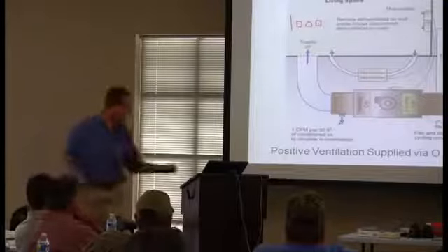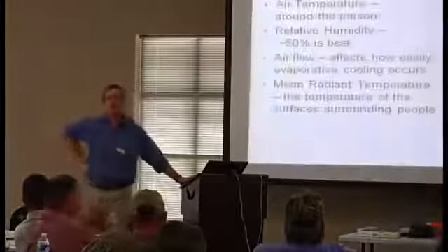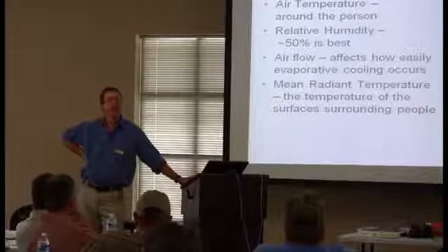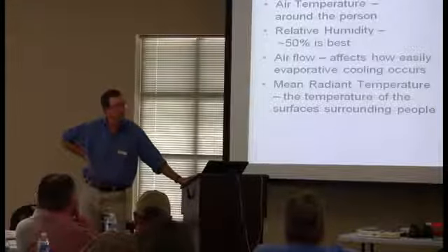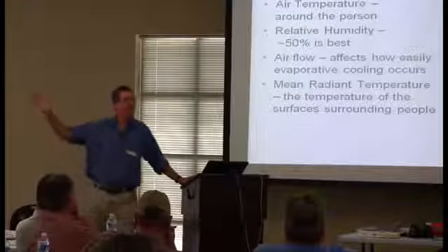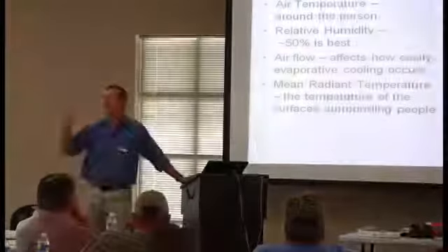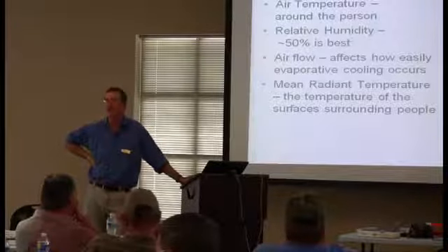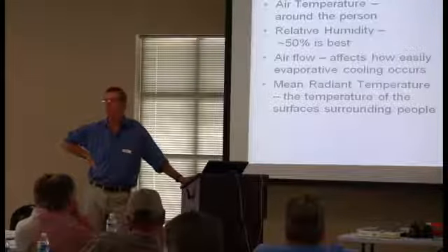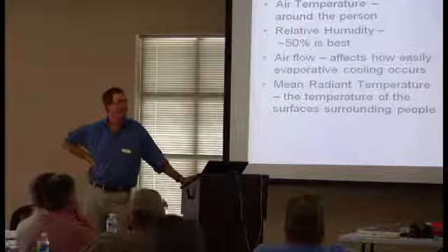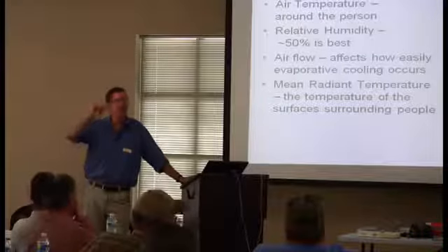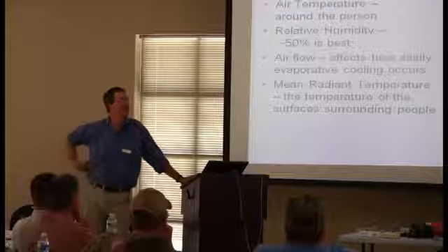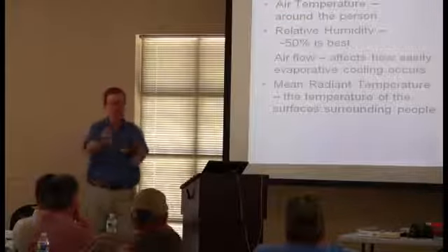All right, we're going to wrap up our building science foray here. Comfort is not just the air around you, it's also the amount of moisture in the air, and the air that's blowing across you. The speed or velocity of the air across your skin affects your comfort. Think about a ceiling fan. Ceiling fans don't actually change the temperature of the air. In fact, if anything, the heat of the motor slightly warms the air, but they make you feel more comfortable, providing a cooling effect because your skin evaporates better.